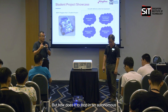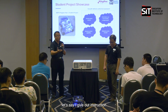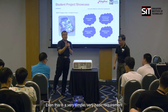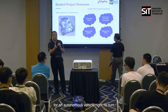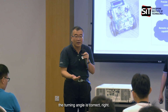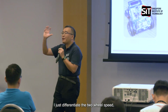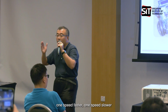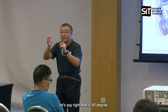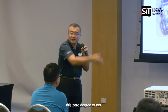But how does it stop in an autonomous way? In an autonomous vehicle, I give an instruction, say move to over there. Somehow I know the path, and I need to turn 90 degrees. Even this is a very simple, very basic requirement for an autonomous vehicle: to turn. How do you know the turning angle is correct? To turn, for this kind of vehicle, is easy: I just differentiate the two-wheel speed. One faster, one slower, so I can turn. But the important thing is that, for example, right now it is 90 degrees and I need to turn to 0 degrees, to here. I need to know whether I already reached 0 degrees or not.